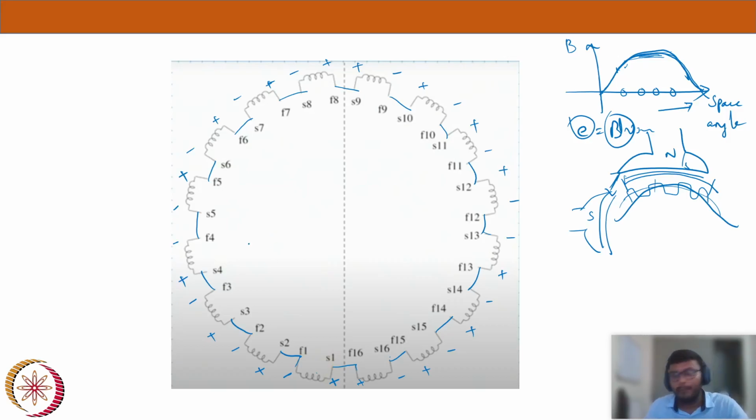So my question is, I want to get a DC voltage out of it. Till now, I have connected all the coils in series, and I have given AC supply, and each coil has been induced with an EMF. EMF is being induced with different instantaneous magnitudes. Now, to get a DC supply from these coils, what I will do is, now here interesting thing happens. Let's see that.